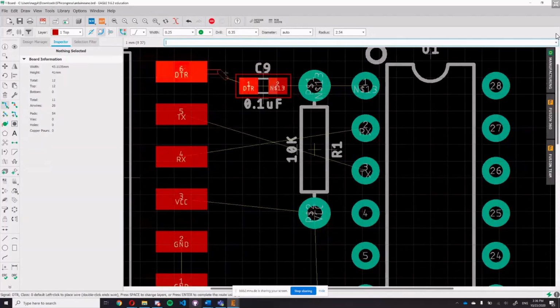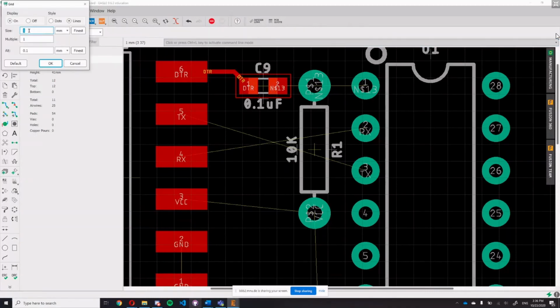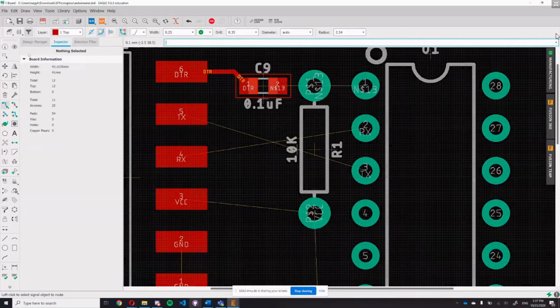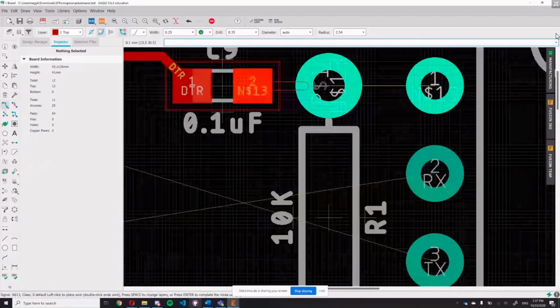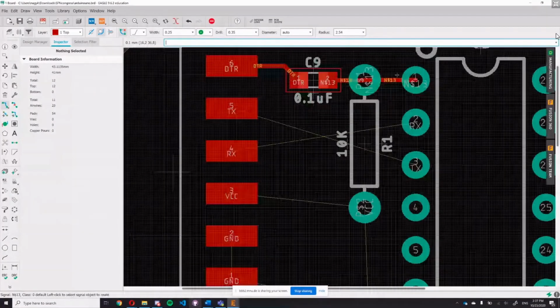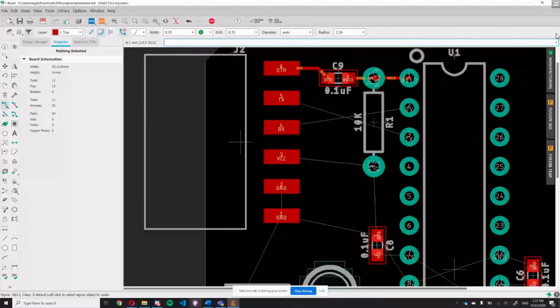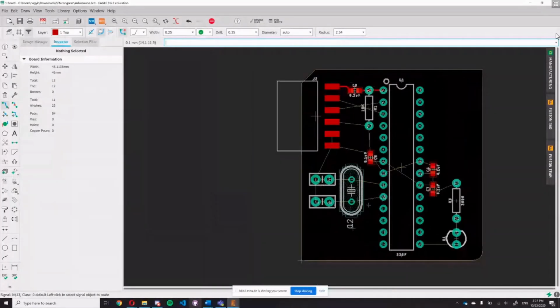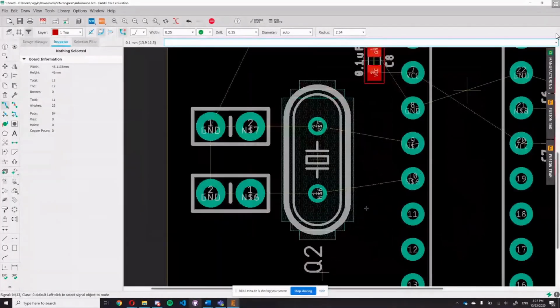This needs to be connected, so you just click here, drag it like this, and connect it. Also for this, I would like a much smaller grid, so I'll go to 0.1 by default, and 0.05 can be the old version. So now you can move much more precisely. Then connect this. You can do this pretty fast because it's guiding you.